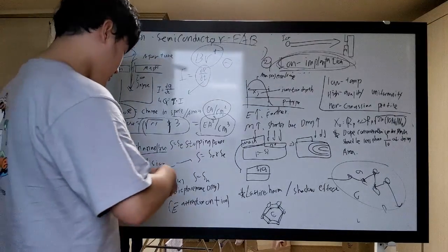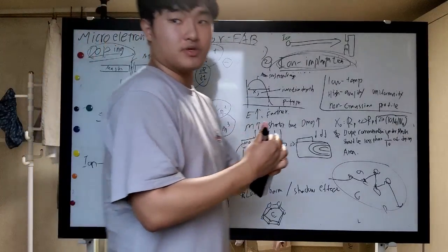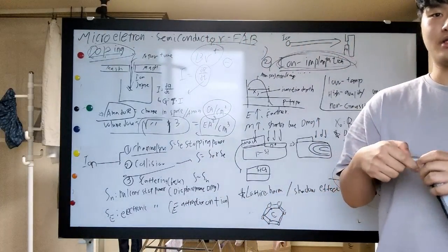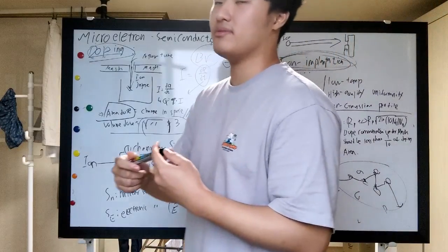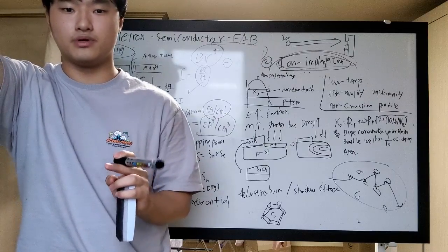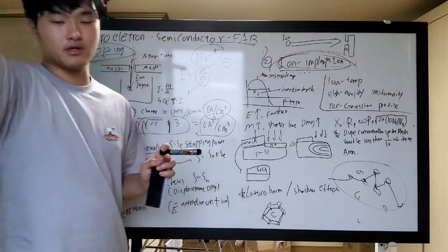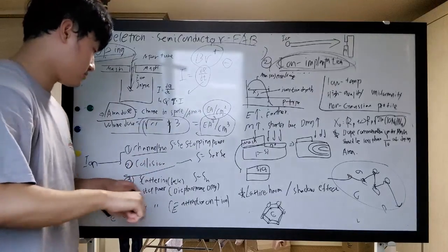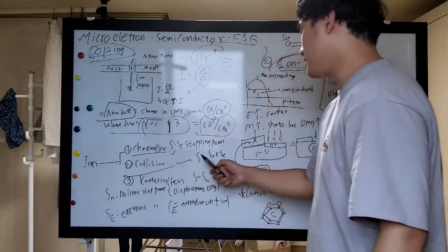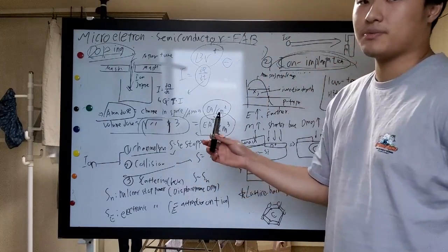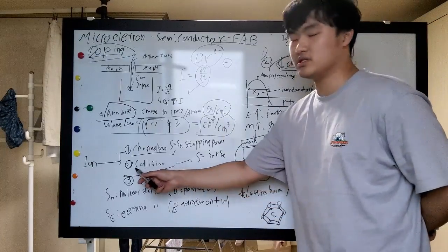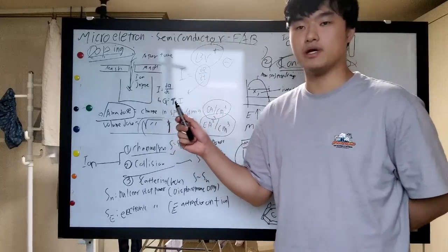So with the collision and channeling, or even the backward scattering, we know there is a stopping power related to letting the ion stay inside the doping target. The stopping power S is related to the nuclear stopping power and the electronic stopping power.